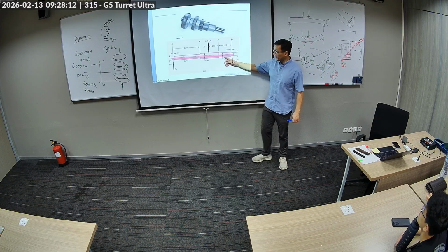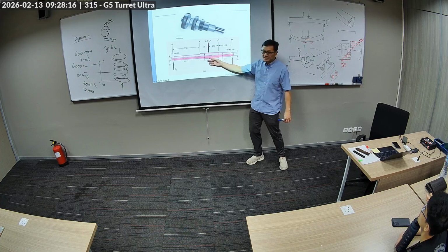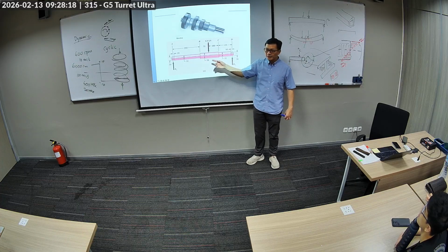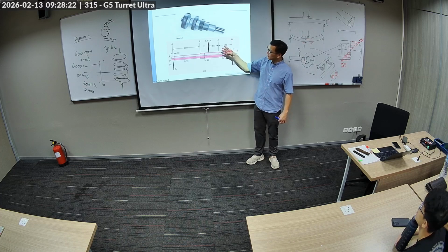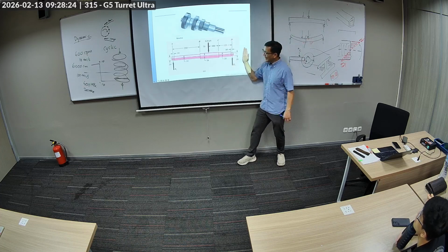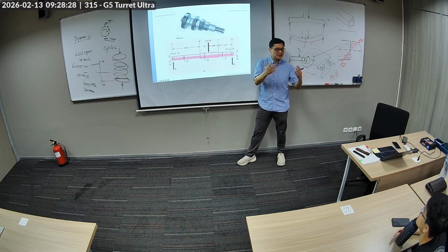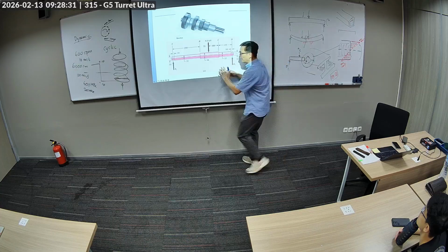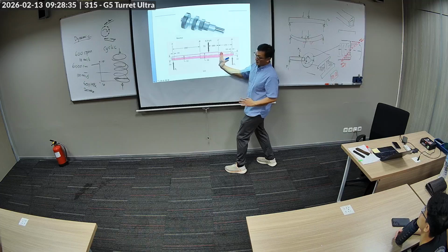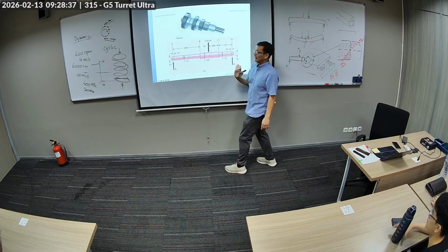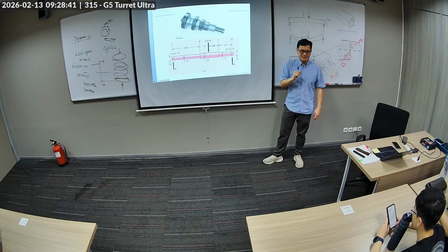By the way, you know why we have these different diameters? Who can tell me why we have these different diameters? Yeah, hint, look up there. So you want to fit elements onto the shaft: gears, pulleys, belts, sprockets, okay? Because we want to put things on it, and it needs to be axially positioned. The easiest way, just make a step like this.